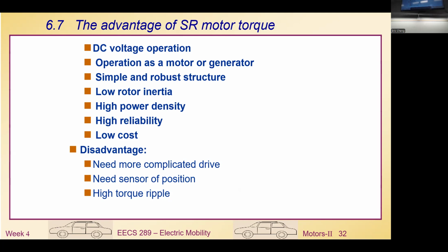And as long as a motor has low inertia, that means dynamic performance, how to speed up and how to reduce speed, will be much faster than all the other motors. For instance, a DC precision motor has a permanent magnet in the rotor, which can increase the inertia. Now, the industrial motor's rotor does have rotor winding that can also increase the inertia.